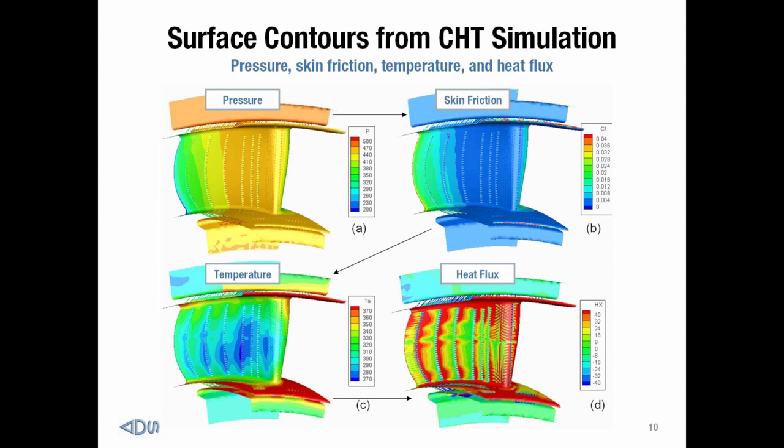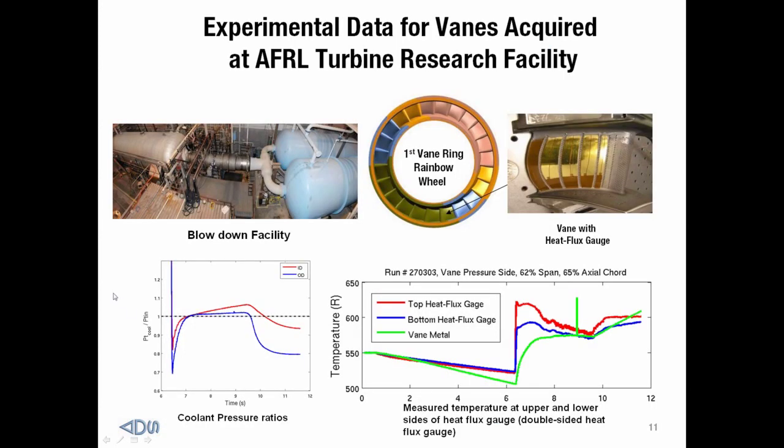Now there's really two interesting phenomena to look at on this heat flux plot. One is, if you recall earlier when we were looking at the streamlines, where those shower head holes point at each other, there was a buildup of cooling fluid. And you can see that pretty clearly on the heat flux along the center here. You see this large region of lower heat flux that builds up. The other thing of interest is you can see the stagnation line pretty clearly in the middle of this shower head region. There's a distinct red line running through here, and if you look at the tails from these shower head holes, you can see on either side of that red line they're pointing in opposite directions.